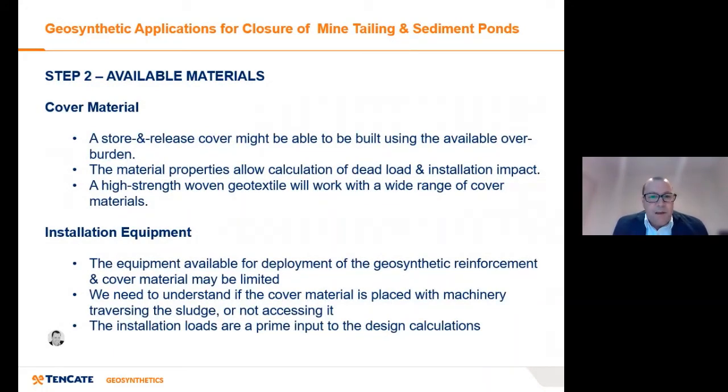Step 2, determine the loads, and the loads are coming from 2 areas, one of which is the cover material that we're putting on top. So that'll be what run of mine waste we have lying around the site that we're going to use in that 1 metre thick layer. And also, if we've got some details around it, we'll be able to understand any installation damage, strength reduction factors and so forth that we can use.